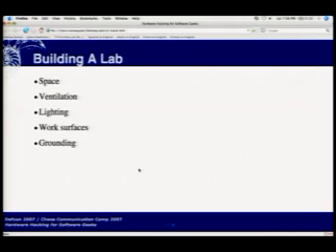Well, in addition to the space, it's also very important how you set up the space. So if you have a table like this one here, you're not going to want to put any electronics on it, because this is a tablecloth. And as I'm sure half of you in here have heard of ESD, electrostatic discharge. You won't know if ESD has damaged your device unless you hit the lottery, and basically it makes it not work at all.